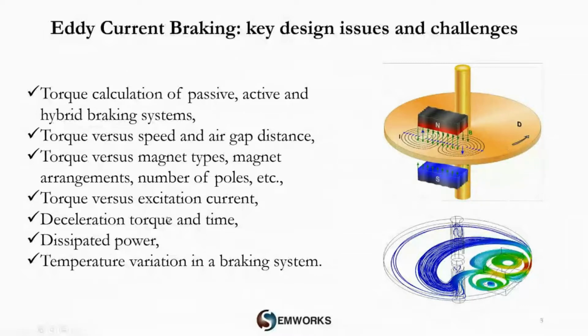Then you talk about the deceleration torque. Okay, fine, you now have the necessary torque to stop. How long is it going to take? Is it 1/10 of a second? Because once you brake, you want to stop almost right away, right? So that's also a design issue that has to be optimized.